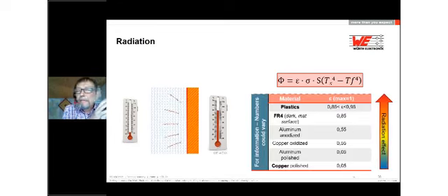So the best material we already said is plastic materials, and dark plastic materials are better than white plastic materials. A dark matte surface is the best we can have for thermal dissipation through radiation. Therefore, for example, we have FR4 material with a dark matte surface. It has a good thing, but aluminium anodized is also not bad.